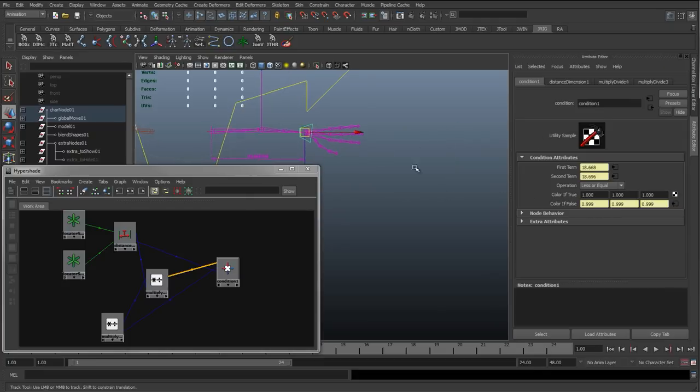So as you can see, if I reset this back to 0, this arm, you can see 80, the first term is less than or equal to that, so it's going to choose 1. So it's going to scale 1. If this goes above, so here you can see the first term is 40, it's higher than the length of the arm, so it's going to choose the false value, which is 2. Because if we say about here, this is twice the length of the arm. So you can see now it's going to use a 2 value for the scale. So if we scale all these joints by 2, these joints would match with that wrist. So it will be scaling the arm as normal, as we'd expect it to be a stretchy arm.